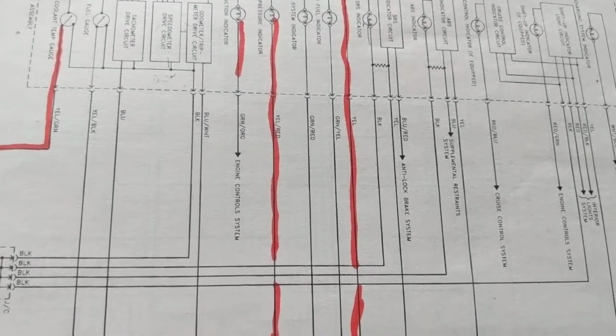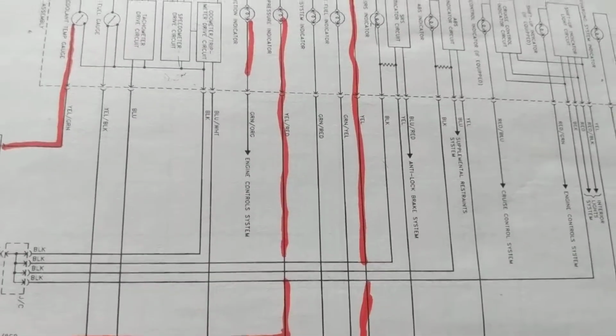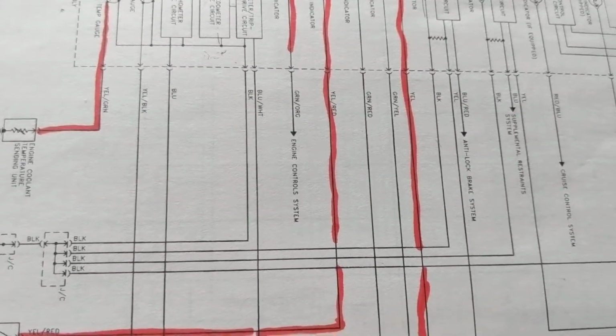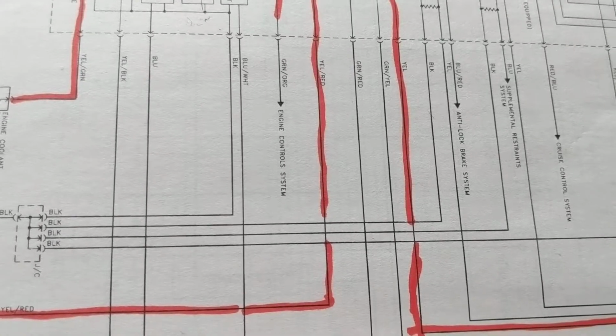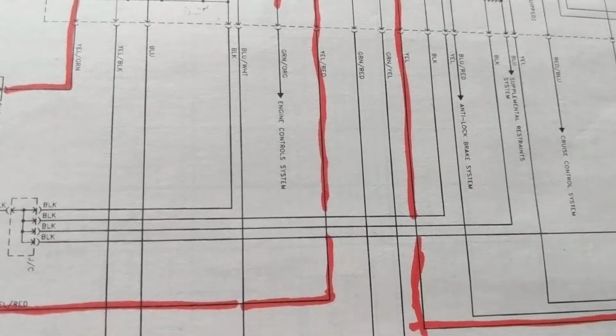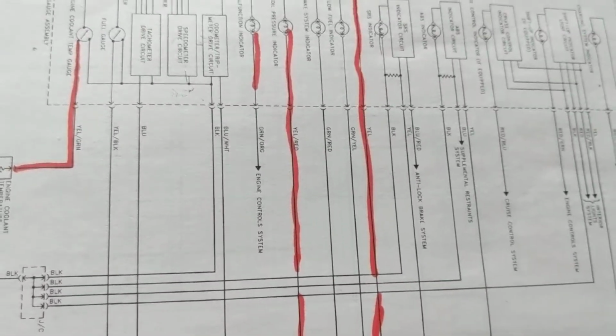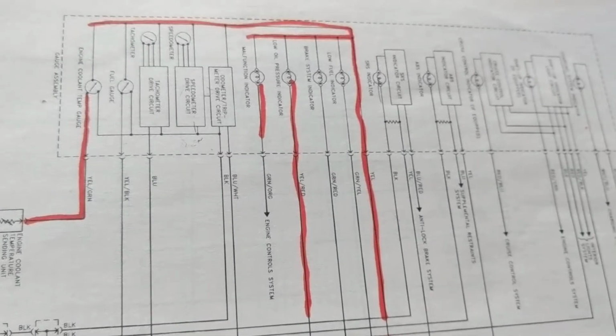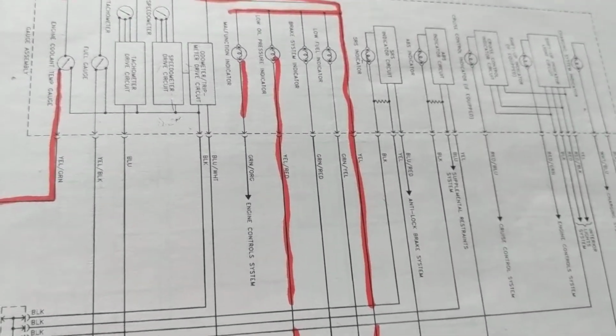If you cannot turn on the lights, which is about maybe 12 amps, something like that, maybe 15 amps, whatever it is, don't think of trying to turn on an engine which requires about maybe 200 amps or more, depending how many cylinders you have. It will never happen, right? The fact that you turn on the lights doesn't necessarily mean I can turn on the engine, and vice versa.